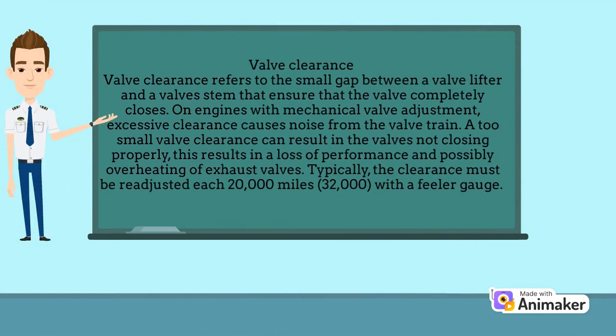Valve clearance. Valve clearance refers to the small gap between a valve lifter and a valve stem that ensures that the valve completely closes. On engines with mechanical valve adjustment, excessive clearance causes noise from the valves not closing properly. This results in a loss of performance and possibly overheating of exhaust valves. Typically, the clearance must be readjusted each 20,000 miles, 32,000 kilometers, with a feeler gauge.